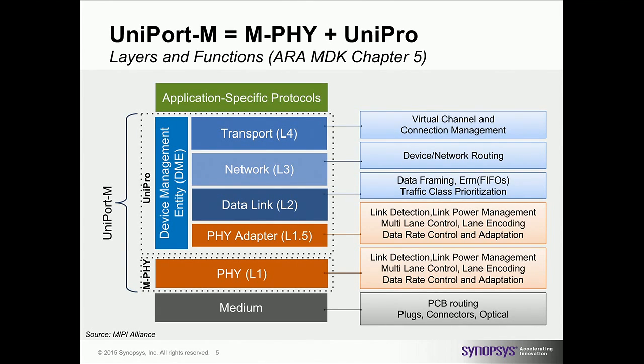And when we look at the connectivity itself, you have the medium, which is eventually going to be the contactless media converter. On top of that, you have the MIPI M-PHY, which is responsible for serialization, encoding, and really electrical conversion of the digital signals to the other side.